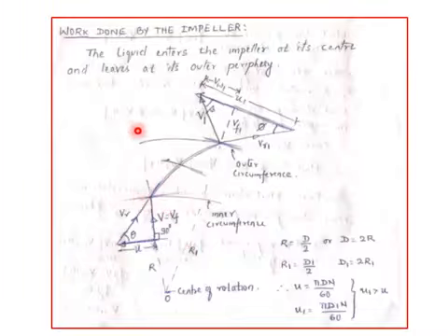So now this is the wheel. We have drawn the tangent to the wheel. So this is the radial direction, whereas this is the tangent to the wheel. Two radial directions come and meet at this point, which is known as the center of rotation. You know that the distance to the inner circumference, this is the inner circumference, this is the outer circumference, is always lesser than the distance to the outer circumference. So that gives r is equal to d by 2, that is d is equal to 2r, and d1 is 2r1. So that's how the tangential velocity, that is u, and here u1 is varying.